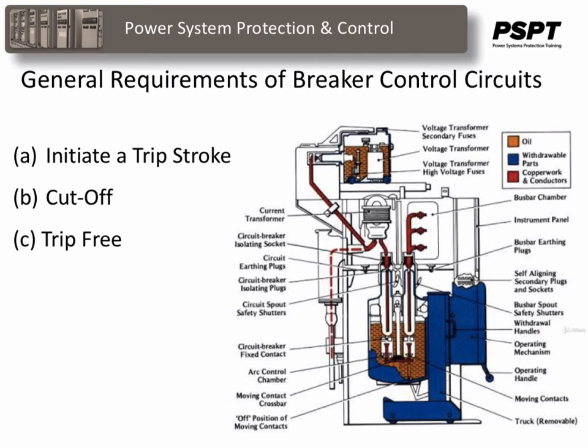The trip-free function. When closing a breaker, the closing device, for example, a solenoid in a solenoid-operated breaker, is energized and the plunger operates through the linkage to close the breaker contacts. At the end of the closing stroke, appreciable time is required to de-energize the solenoid coil. In the event that the breaker has been closed on a faulted circuit, it must be reopened as quickly as possible. If a breaker can trip automatically upon receiving a trip signal before the closing operation is complete, it is said to be trip-free. Various arrangements are provided to obtain trip-free action.